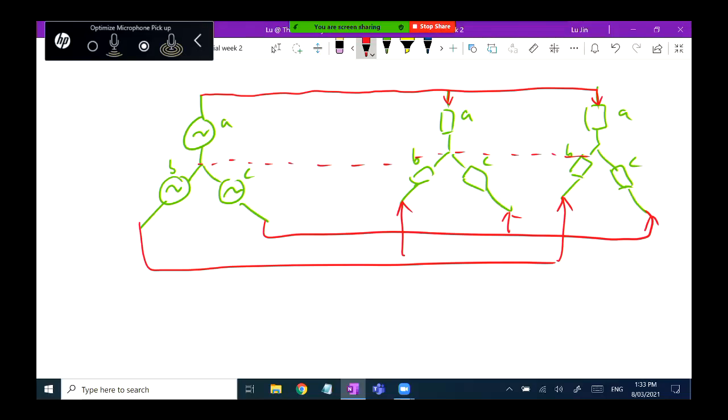But for you to understand how to use the single-phase quantity to calculate the three-phase thing, I think making a connection of neutral points should be easier. For example, if I really just make such a connection, we said it doesn't matter to have or not have this neutral connection for a balanced system. We just make it up. And now we got 4 lines. Of course, the impedance of the neutral connection is useless because there's no current at all.